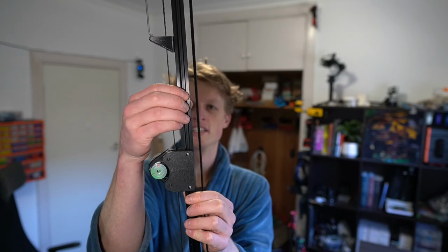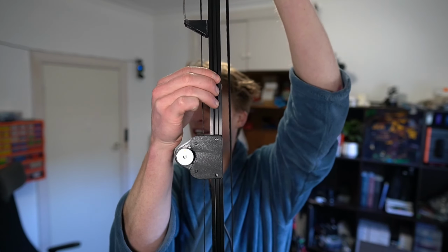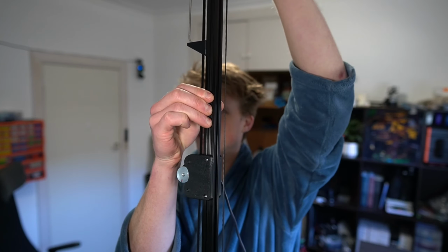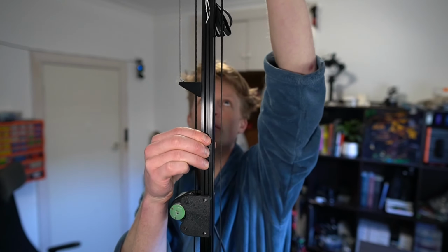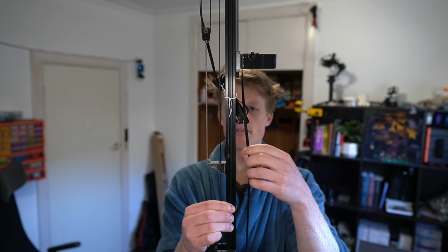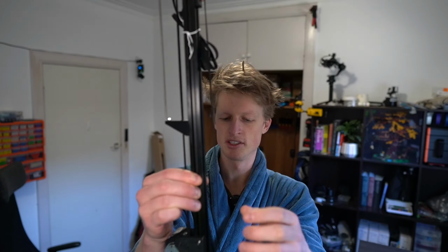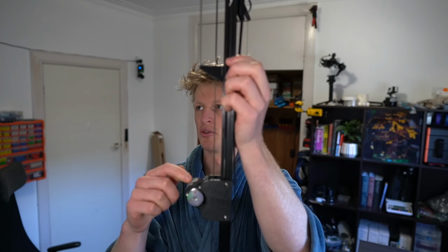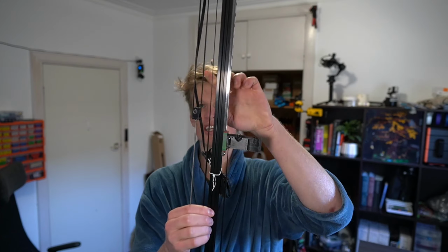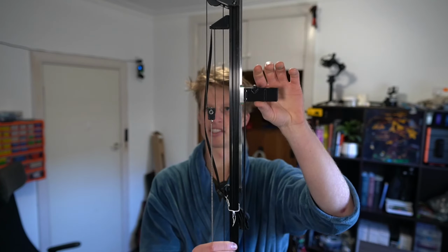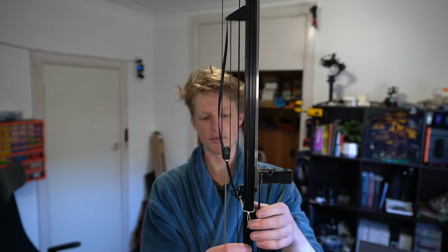And while this moves up and down, it's attached to an encoder. So we've got a rotary encoder down here, and as we slide this, that encoder picks up how far the slider has moved via the belt. So we've got a slider attached to a belt. The belt routes around and goes through an encoder. There's also a spring here and a little pulley system, and that's just here to keep tension on the belt, so that the encoder never misses a step, so that the belt can't slide over the encoder's toothed pulley without turning the encoder itself.